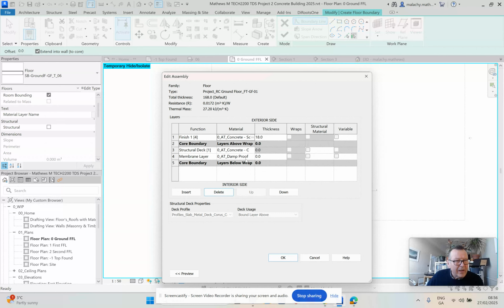We don't really. The only reason you put a damp-proof layer in there would be, again, if you imagine this deck that's going out, we've got the chairs and the reinforcement. You could consider putting a damp-proof layer on top of the deck, and it just helps keep the water in, so that the chemical reaction will take place. I don't think they normally do it because there's too much possibility of the damp-proof tearing. So it's not really worth it, to be honest with you.